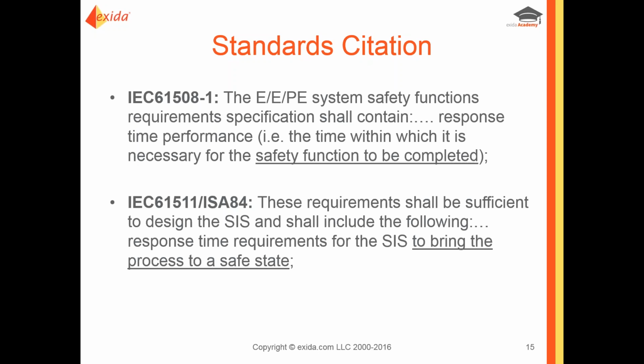IEC 61508 defines timing requirements, SIF response time performance, as necessary for the safety function to be completed. IEC 61511 or ISA 84 takes that a little further in that it brings in this requirement that the SIS bring the process to a safe state.